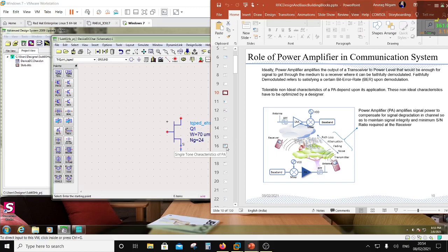So now in a communication system, we have what you call the radio front end, and the radio front end comprises a PA which boosts the power, and an LNA which, once it receives the signal, is going to amplify the signal without adding any of its noise, right? So it's called a low noise amplifier. So low noise amplifier and power amplifier, they are the key components of a radio front end. They basically are involved in scaling the powers, right? And another thing is that the antenna is a radiating element. Both transmitting antenna and the receiving antenna is a reciprocal of that. It's a receiving element, right?